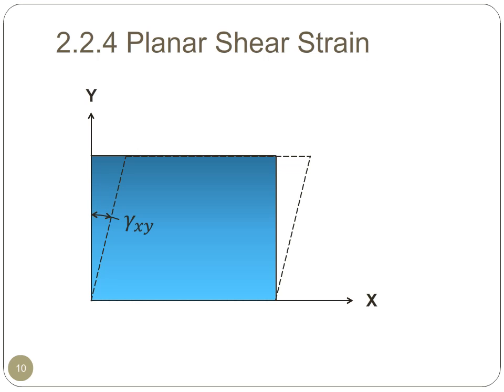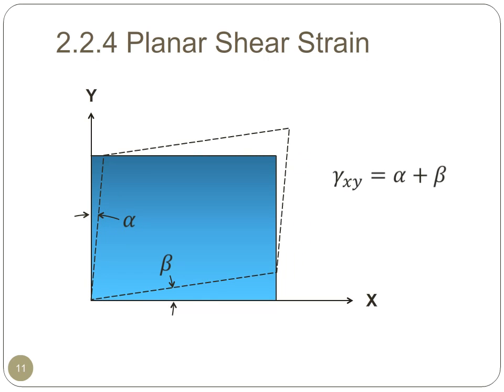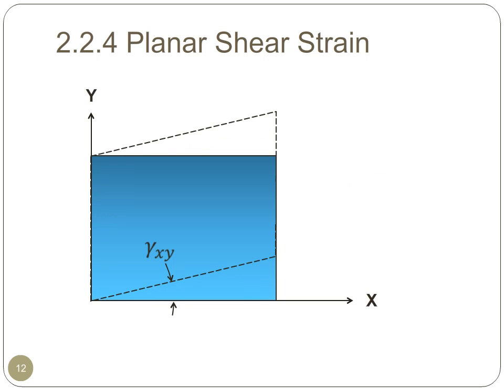Since the shear strain is just a measure of the change in angle, this shear strain is equal to this shear strain, where the angle is divided up into two angles relative to the x and y axes, and this shear strain, where we're just measuring the angle relative to the x-axis. In all of these examples, the area of the rectangle hasn't changed.